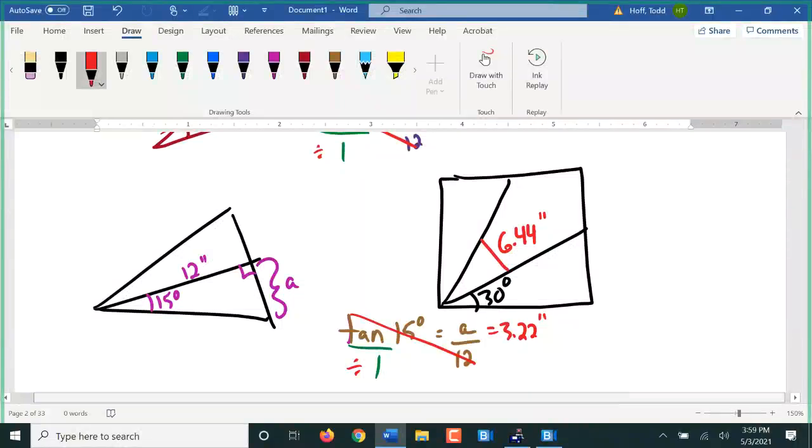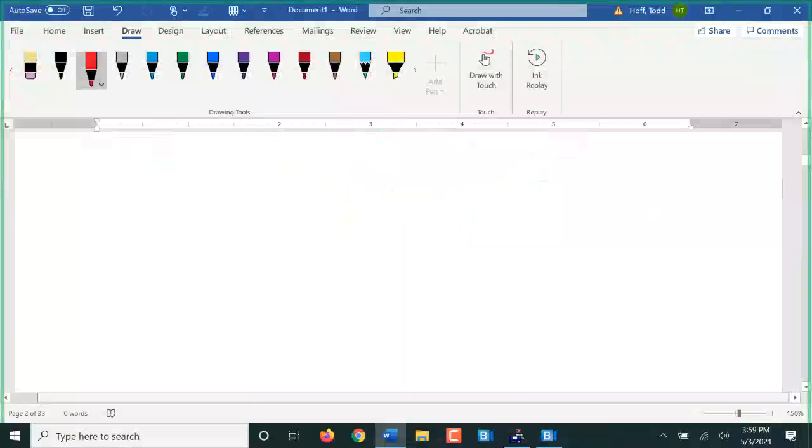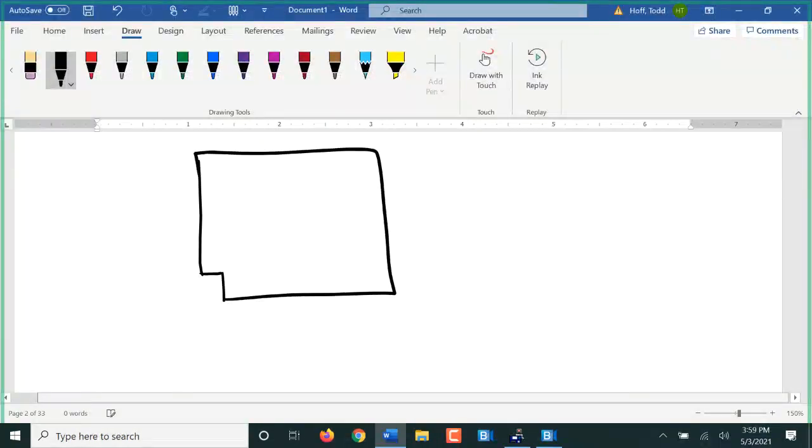How do we get around it? We notch the winder. You're going to have to have some sort of a newel post in there anyway, if there's a railing or whatever. You notch it. How far do we notch it?